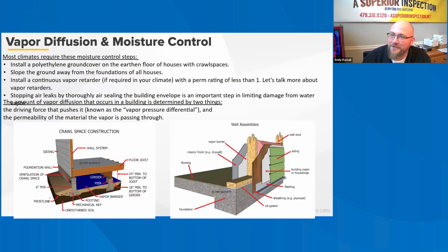Vapor retarders are often applied in a crawl space of a building to prevent ground moisture from evaporating and traveling up into the home. Many building codes require applying such vapor retarding materials under wallboard to prevent vapor diffusion from bringing water into the structural assemblies. In cold climates during the heating season, pressure differential drives the vapor from inside of the building to the outside.